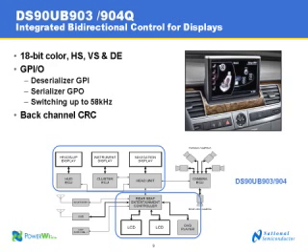Question that just came in: does switching to 58 kilohertz mean 58 kilohertz pixel rate? No, it doesn't. This is referring to the speed of the general purpose I/O switching. Okay. The pixel clock rate, remember, is coming from the serializer, the forward channel, and that can go up to 43 megahertz pixel clock. Okay, gotcha. And the switching rate for those GPIOs is a feature of the bidirectional control channel.